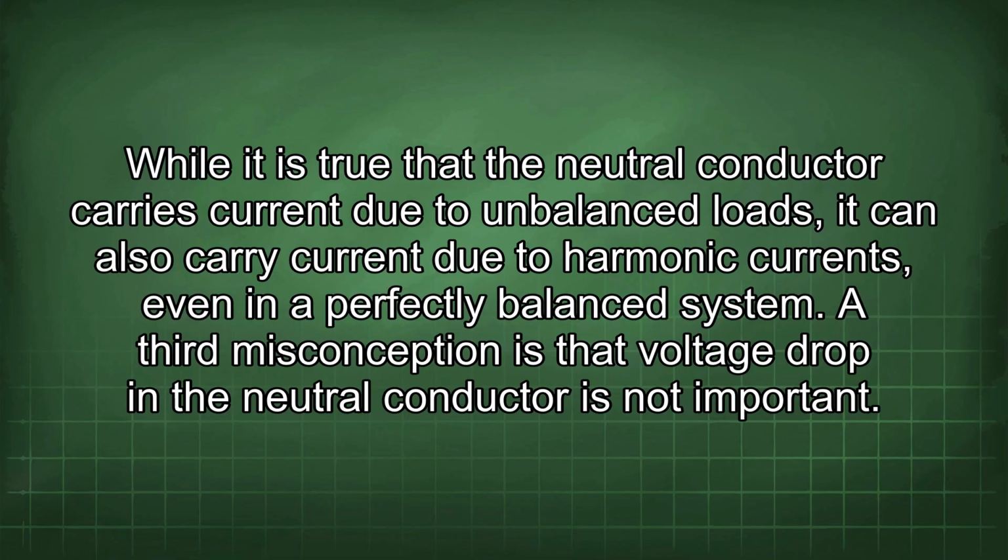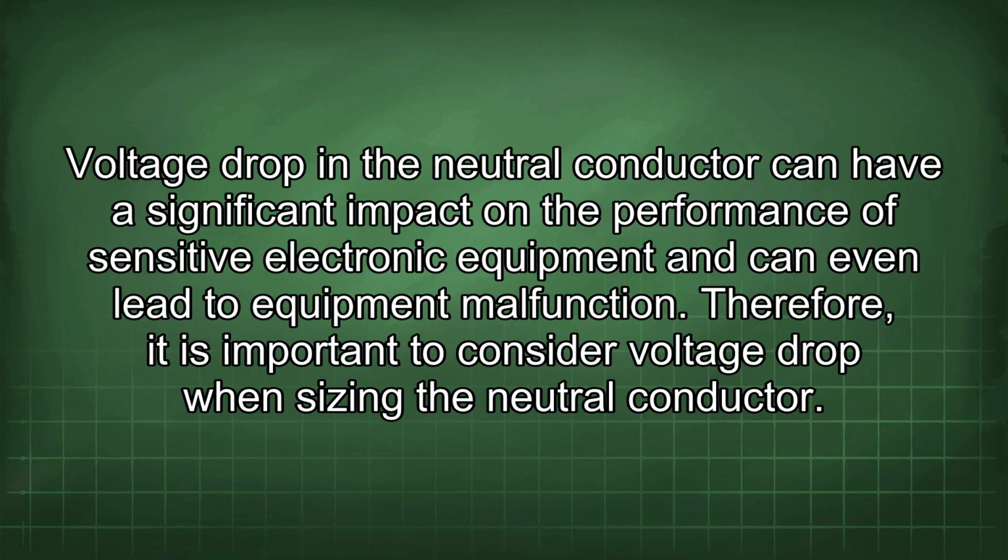A third misconception is that voltage drop in the neutral conductor is not important. Voltage drop in the neutral conductor can have a significant impact on the performance of sensitive electronic equipment and can even lead to equipment malfunction. Therefore, it is important to consider voltage drop when sizing the neutral conductor.